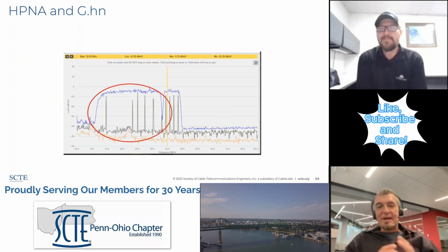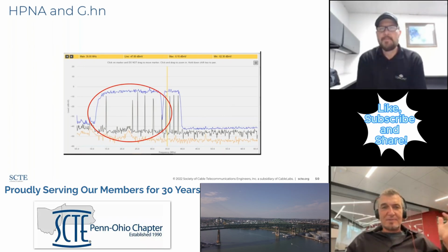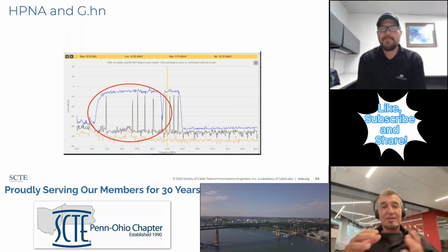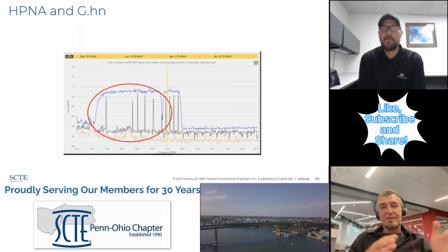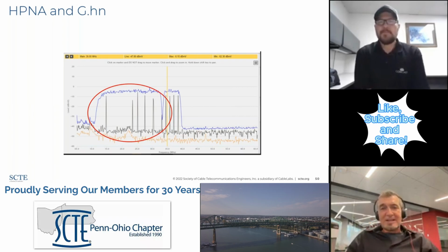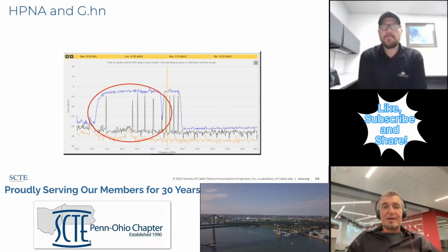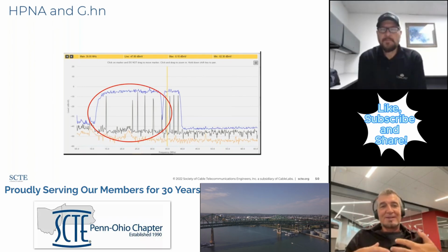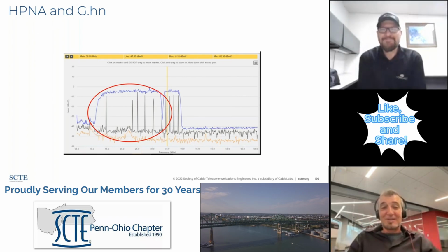You bet. So both are actually, it used to be called HPNA, which is Home Power Network Adapter. I think there's a couple of variations it's changed. And then G.hn is a new standard that has surpassed HPNA, has been absorbed into G.hn. It's basically an OFDM signal that's used by competing technologies that ends up on our coaxial network when it's not supposed to be. So for example, think about the way that MoCA works.